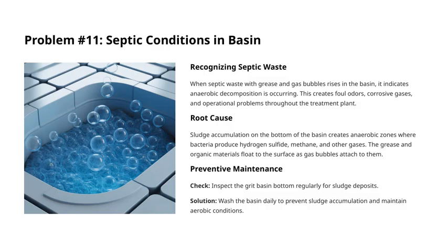Let's talk about problem 11, septic conditions in the basin. Recognizing septic waste is crucial. When you notice grease and gas bubbles rising in the basin, that's a clear sign that anaerobic decomposition is happening. This process produces foul odors and corrosive gases, which can cause operational problems throughout the entire treatment plant.